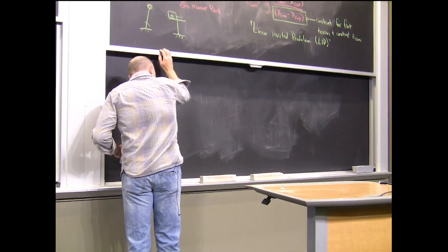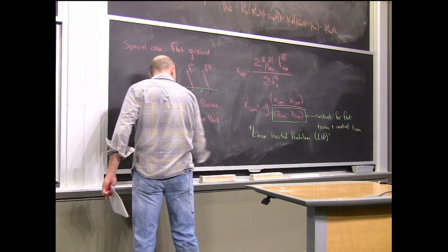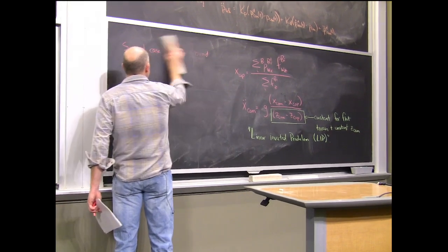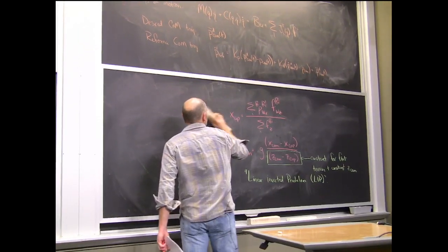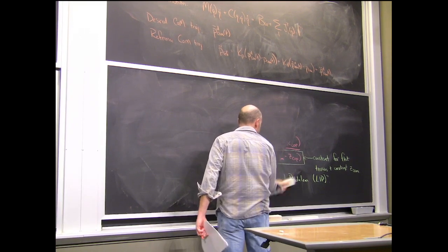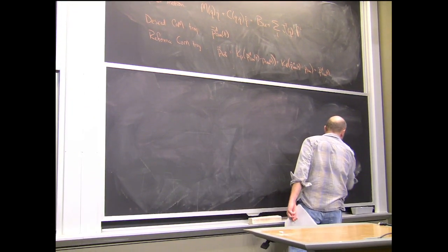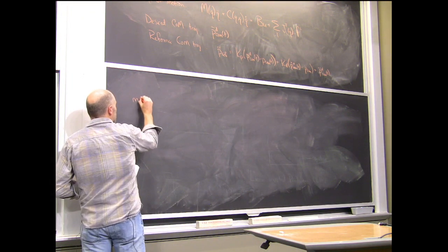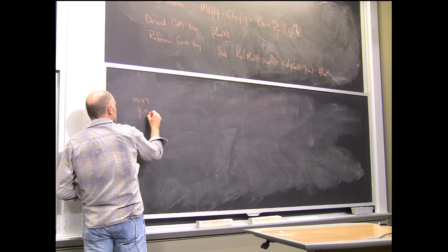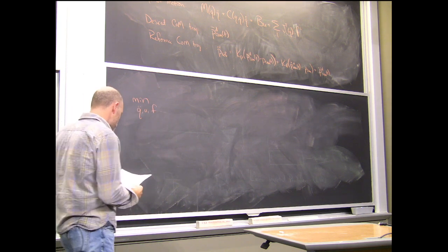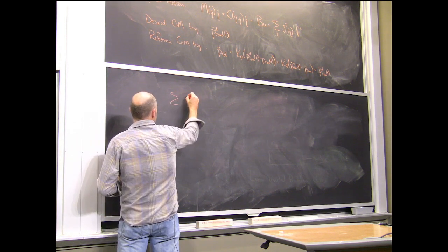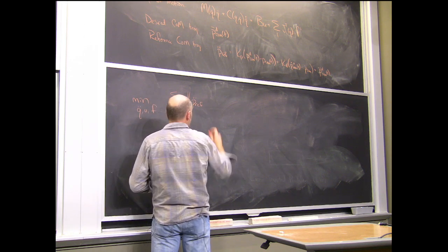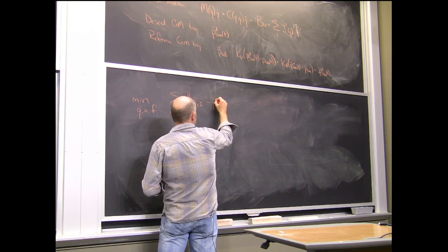And what we do is we solve a small optimization problem at every time step while the robot's running, which doesn't solve the full optimal control. It just solves the instantaneous control that you need to be as close as possible to the reference acceleration. So we say find me Q double dot, U, and the forces that minimize the difference between my reference acceleration and my true center of mass acceleration.